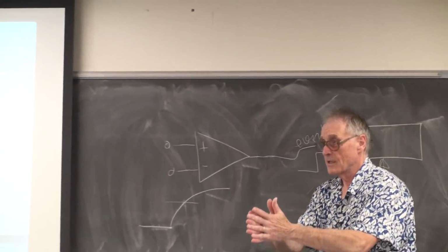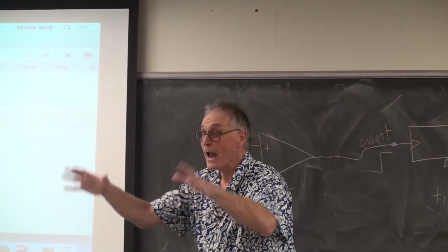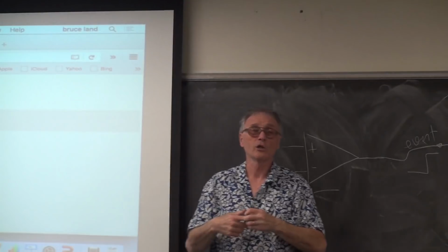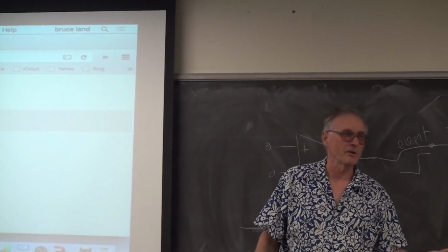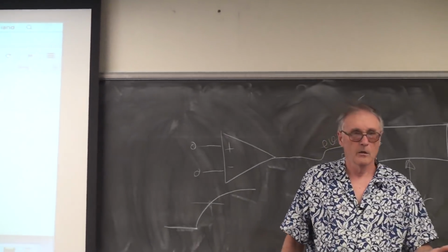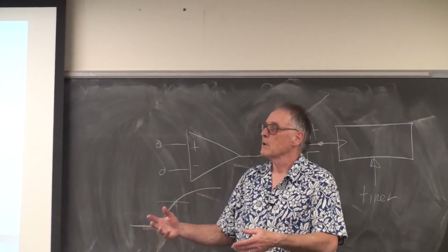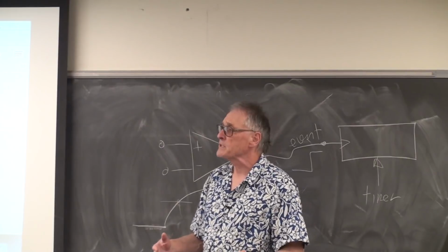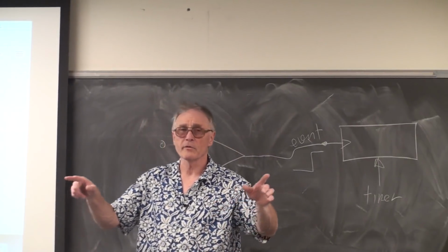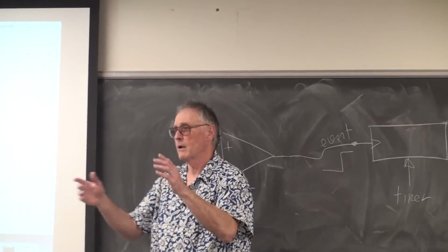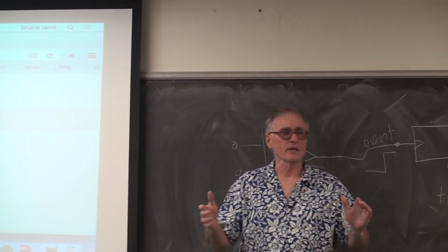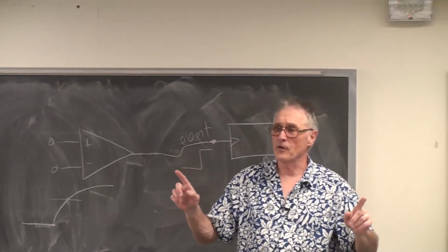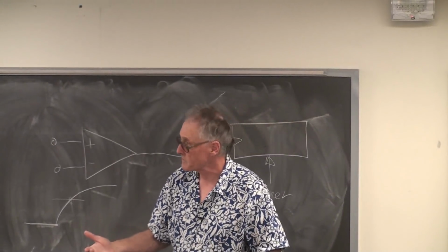The goal of this course is to figure out how to use all of this hardware at the same time to do some function. Right. Now, clearly, you're not going to use every single unit in every single application. Motor control might use more PWMs. Instrumentation might use more input captures. Let's say you're measuring sonar channels. Let's say you have an array of microphones and you're trying to get the direction of the gunshot. Well, let's settle for a clap. You're trying to get the direction of somebody clapping. So you need to measure the arrival times from different microphones. That would be a clear way of using input capture to get times, right?